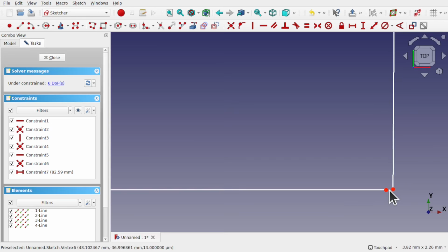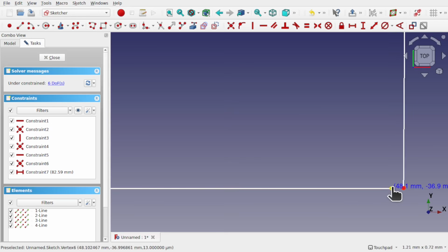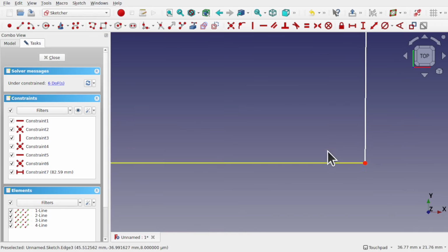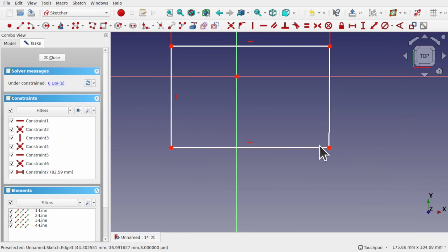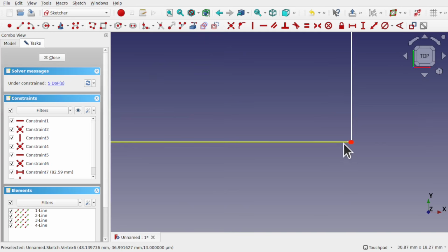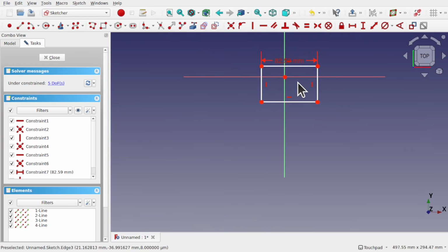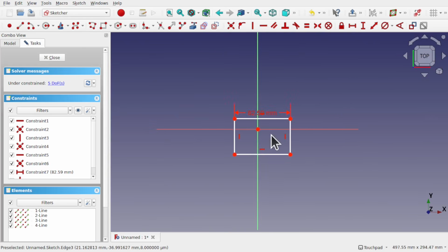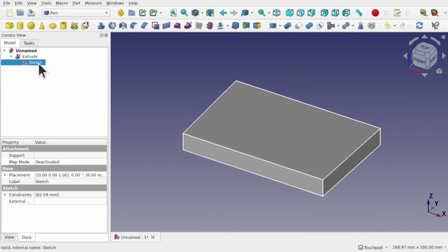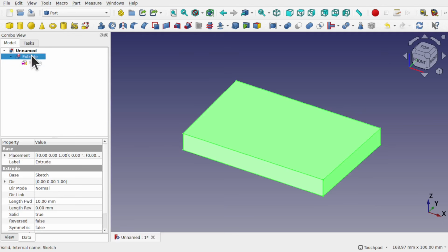So you can see that I've zoomed right in, but I've left some space in here. When I zoom out, it looks like these 2 points are coincident, and we add the constraint. And you can see that, well, they have moved apart, but that is really easy to miss. If we zoom out, it looks coincident, we look okay. Hit close, we get this exclamation mark. Why is it not closed? The extrude, if we come down and set the solid to false,